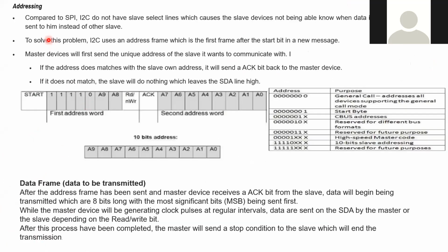Okay, so now the next one is addressing. We all have some addresses, which have a general purpose. Some of the addresses are the address of a particular slave. I told you a 7-bit address is there as well as an 11-bit address. Maximum it can occupy an 11-bit address. So you all understand, first, I can send only not one single address.